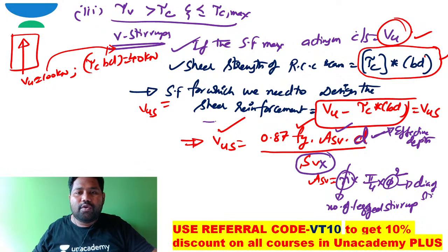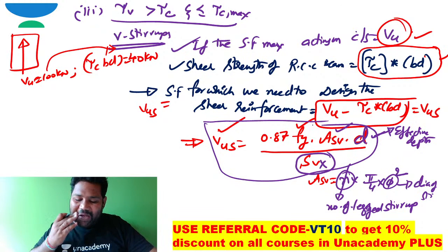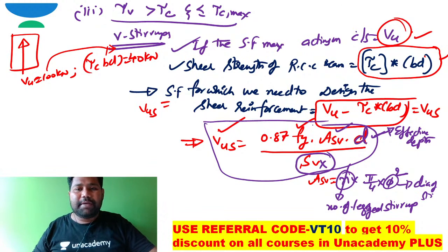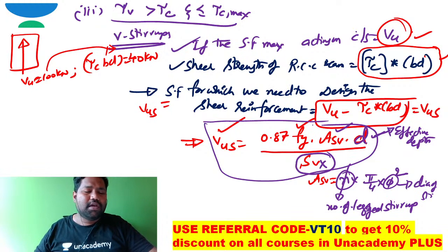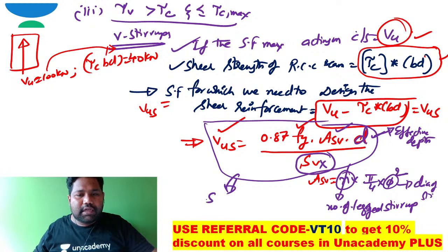So from this one and only equation, can I work out the spacing of shear reinforcement or not? If you provide the diameter of the stirrup, two-legged stirrups of 8 millimeter or whatever that may be, you are able to fix this spacing. So from this, Sv can be found out.